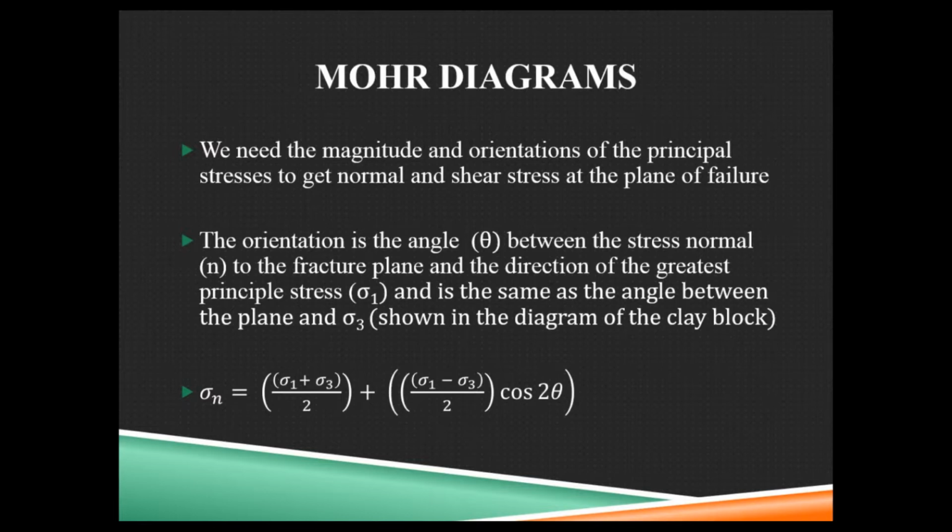In the lab, this is easy. Air pressure is usually designated as 0 because it's 0 gauge pressure, for sigma 3. Sigma 1 is whatever stress you're applying, so you know how much it is. The angle of the plane of failure, easy. It failed, you have it, measure it.